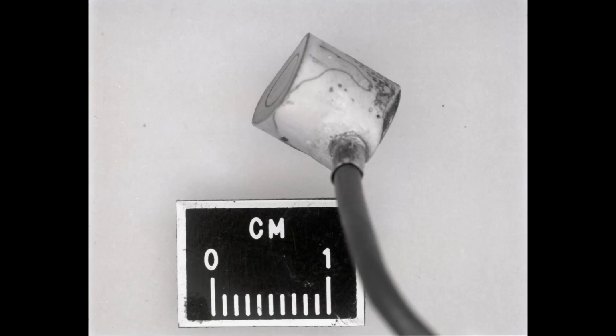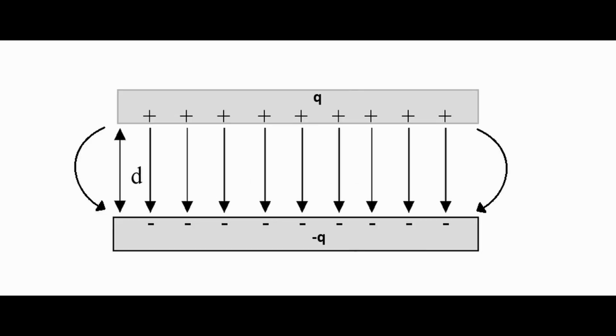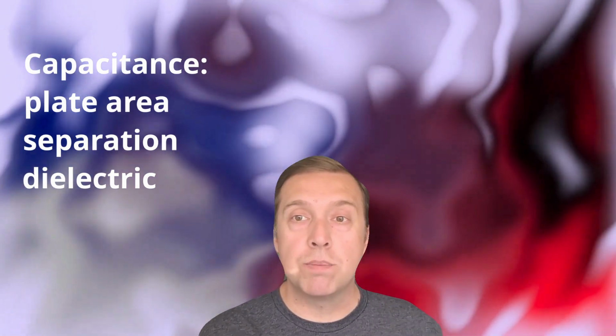Another type of sensor to detect physical displacements is called a capacitive sensor. Capacitance is a property of a capacitor element that relates the amount of charge the capacitor can hold for a given voltage. A simple capacitor is just a pair of separated conductive plates. The capacitance is completely characterized by its physical specifications of the plate area, the plate separation distance, and its contained dielectric material.